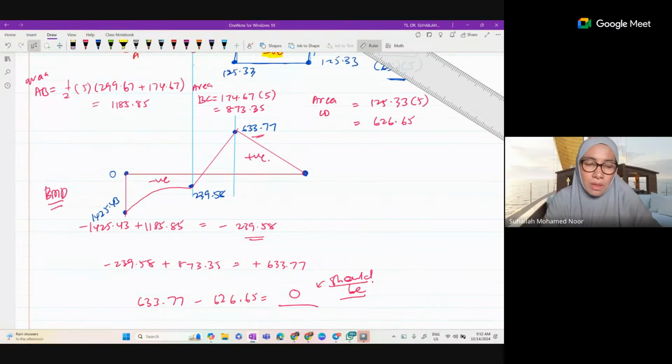Okay, so actually, from this bending moment diagram we will get the shape of the displacement or deflection in the beam, and the maximum moment. The maximum moment shown in the bending moment diagram is where we will put all the reinforcement when we do the design later, in the design subject. Okay, so this is how we get the shear force diagram and bending moment diagram.